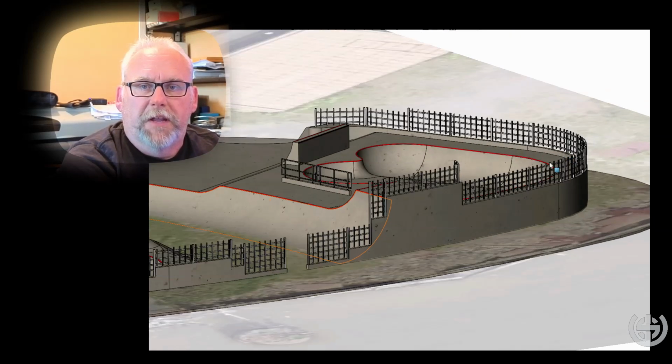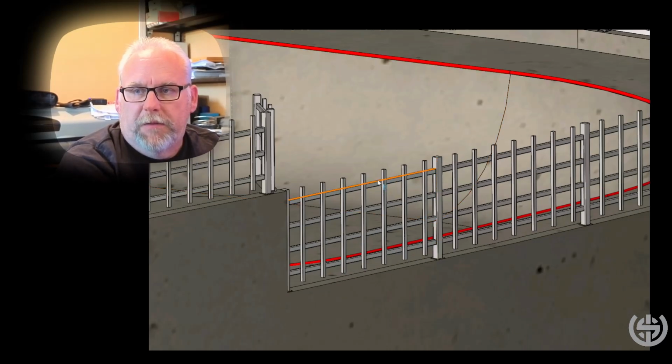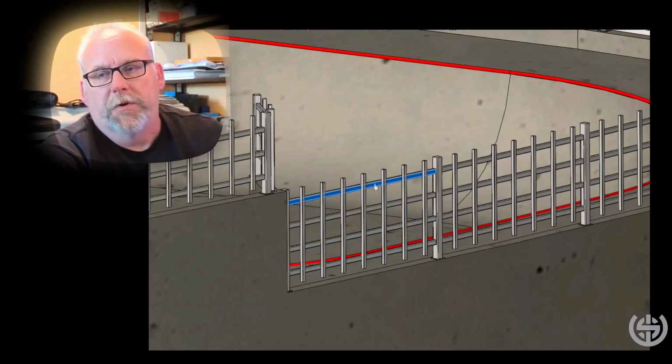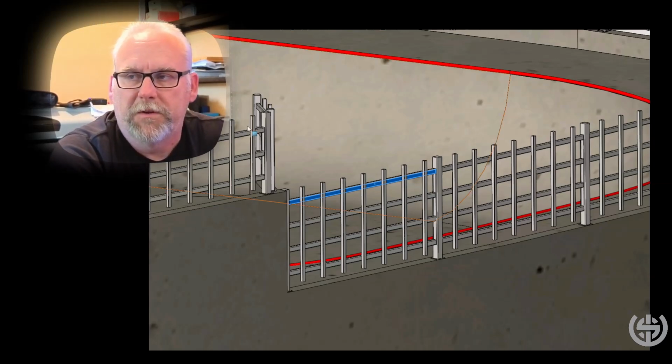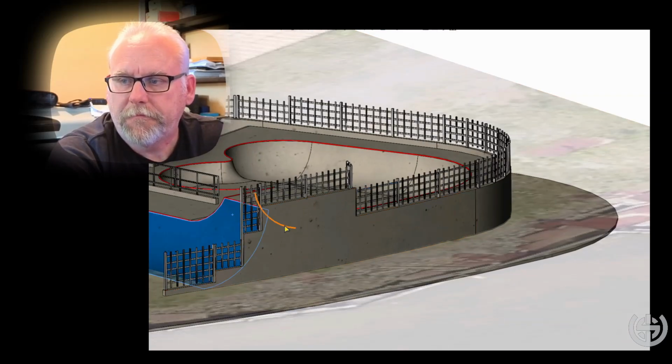Certainly in this elevated area, I would absolutely have fencing all along here. Don't want people falling. I would actually probably eliminate this top bar right here. I would make the fence non-climbable, I would reduce the climbability of the fence. That way you reduce the ability to fall off of these taller areas.